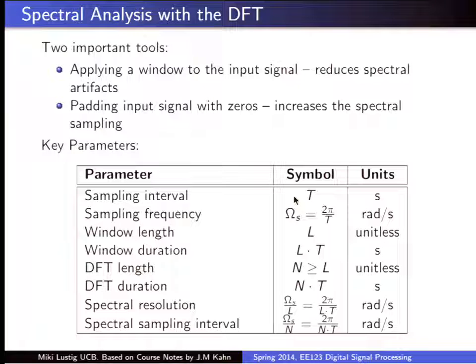Okay. The DFT length is going to be of size N, that could be equal to the size of the window, but could be bigger than the size of the window. And when it's bigger than the size of the window, that means I'm zero padding. So I did take a window of the signal, but when I compute the DFT, I might compute it over a larger range, only I'm going to zero pad it. Okay? That's strange.